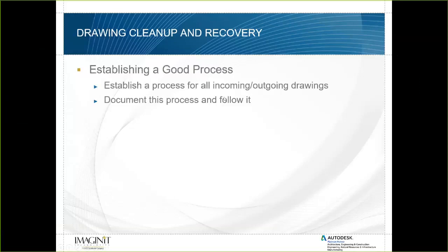So I always refer back to this: establish a good process. Establish a process for all incoming and outgoing drawings. So if you work with people who send you drawings that you need to use, I highly recommend putting in a process to go through and do the minus purge, the purge, get rid of all the extra garbage out of their drawings that you don't need or want to contaminate any of your drawings with. And then save their drawing as like a dash clean, something like that. So you're not modifying their original information. You keep their original file, but you have a clean file that you're working from. Document this process and always follow it when you have incoming drawings.